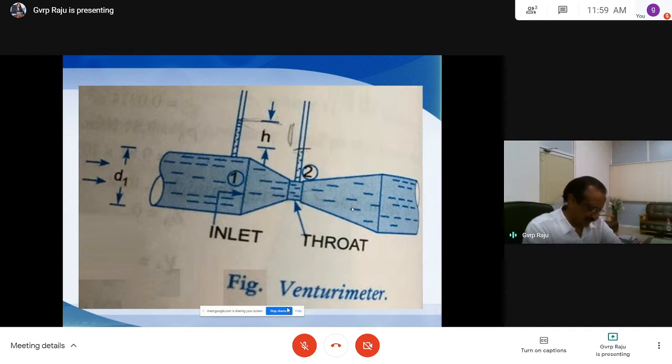The reason here is, from here to here the velocity is reduced. This part we are only taking for pressure measurement. When you reduce the cross-section area, a pressure difference is created. And again there will be acceleration here, acceleration meaning the velocity increases. When you go from here to here, let us say here the velocity is V3, there will be deceleration. In other words, the velocity is reduced.